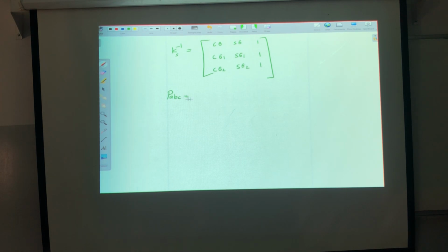So this will be VA IA plus VB IB plus VC IC, which equals VABC, of course I'm discussing stationary, multiplied by IABCS as matrices. Now, someone will say, I need to find the power in the QD reference frame. Can you give me a relation for the power?